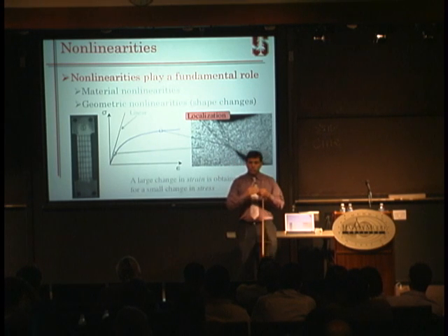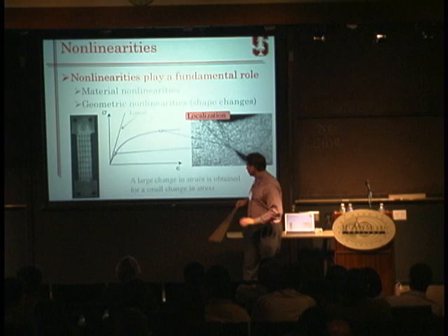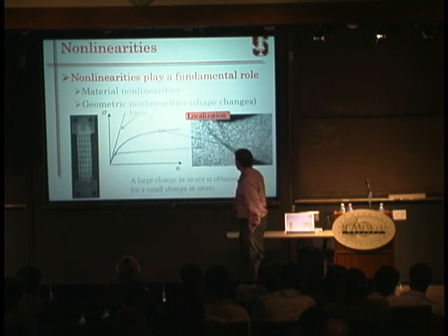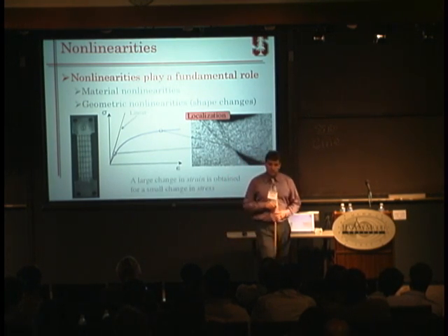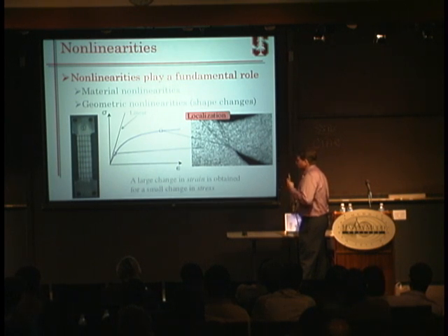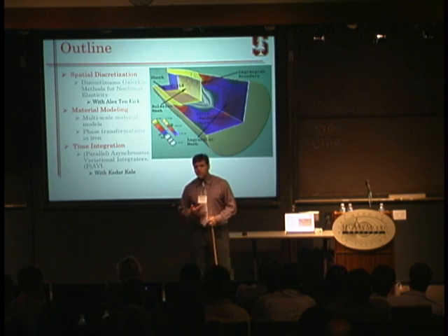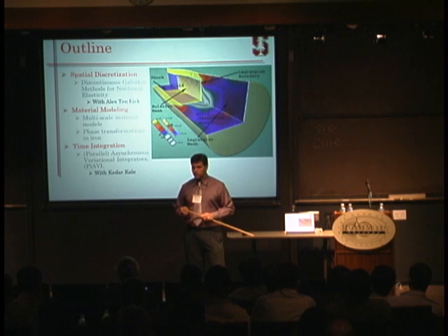That means that if you push your material a little bit farther in the deformation, any little bit of stress or force that you want to get out of your material in this area will deform your material a lot more. And that's why the deformation localizes there. So in dealing with solid mechanics problems in large deformations, you need to be able to somehow capture these nonlinear effects. And I have more examples later on.